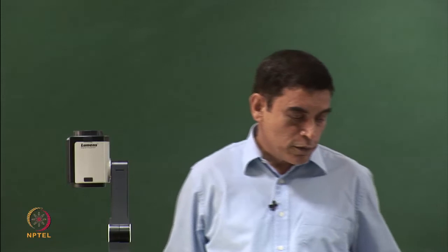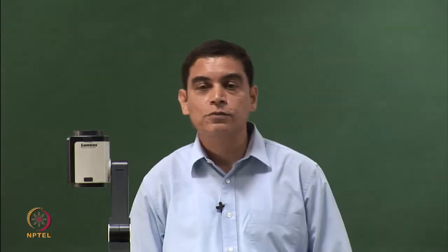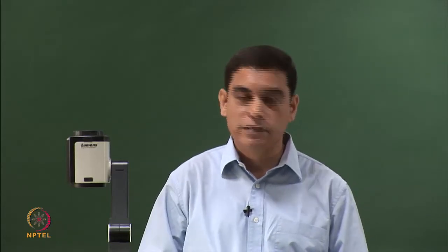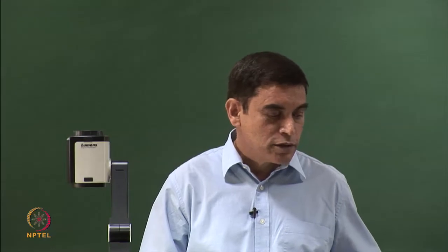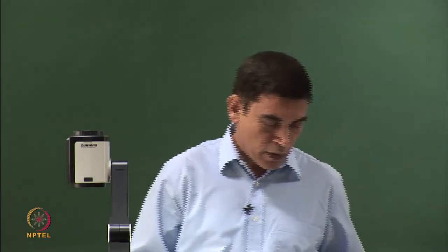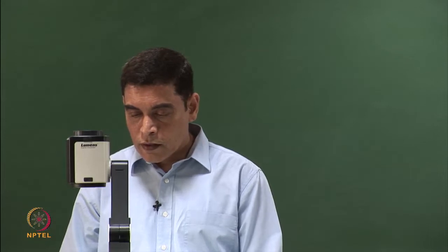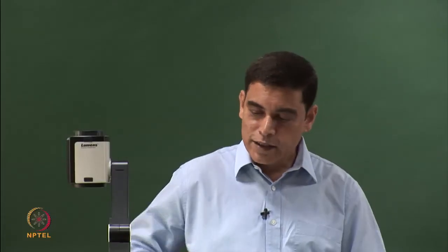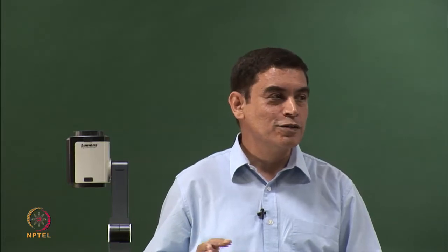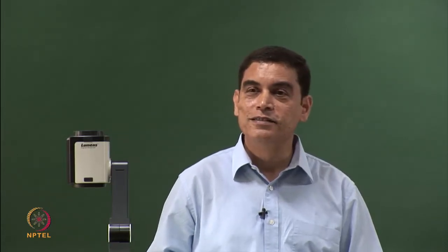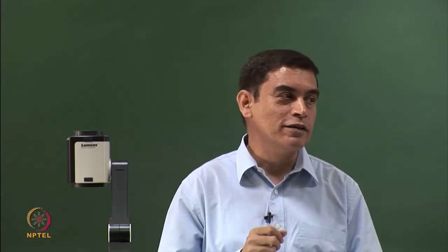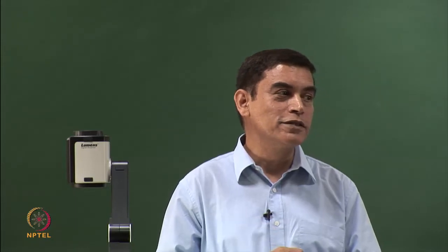So this took care of one set of problems, and this did not require so much vibration analysis as it required doing a pure mechanical verification using bump tests. So where did this knowledge on vibrations come in handy? So we did something called a rap test. Have you ever heard of a rap test? So let's say I hit this and it vibrates. This is the closest demonstration of a rap test. So you have a tube, it has a natural frequency. To get to the natural frequency, you excite it and then leave it to vibrate, and you measure that frequency.